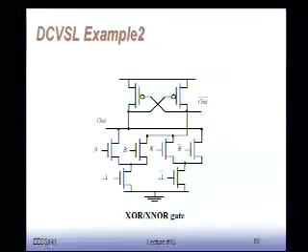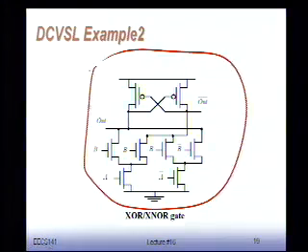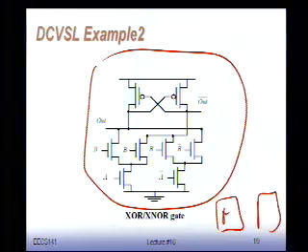Very good example. This is the most nasty gate of all of them. XORs are always a pain. If you have to do CMOS XORs, it's really painful to do so. Here an XOR is a quite simple function. And actually you can even be cleverer. What this has done is make sure that you can implement F and F bar totally separately.